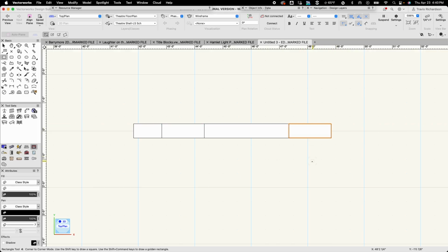There we go. Those are going to be all of the different segments of information that I'm going to be putting in. The next thing I'm going to do is activate my line tool, and I'm just going to draw a 6-inch line from the center left smart point of the leftmost rectangle coming out 6 inches. That line is going to designate exactly where in space the pipe is.